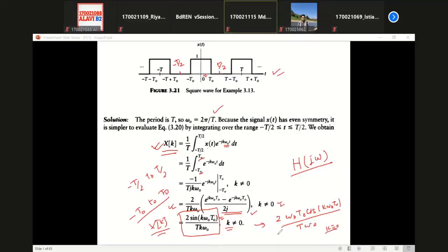So this is actually nothing but the average value of your signal. Is it not the average value for k equal to 0? For k equal to 0, you are getting the constant term x0. And if your k equals 0 in this expression, then this integral will be 1 by T, integration from minus T by 2 to T by 2.